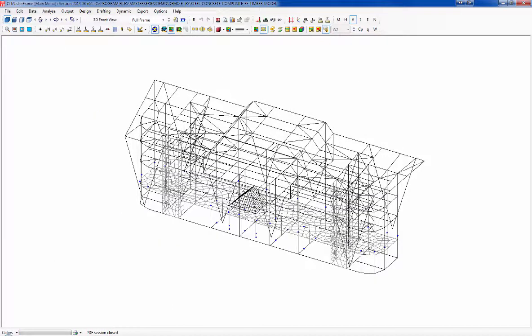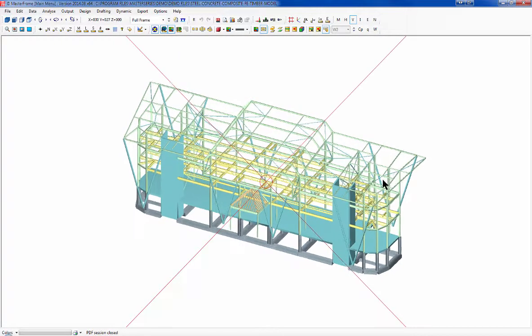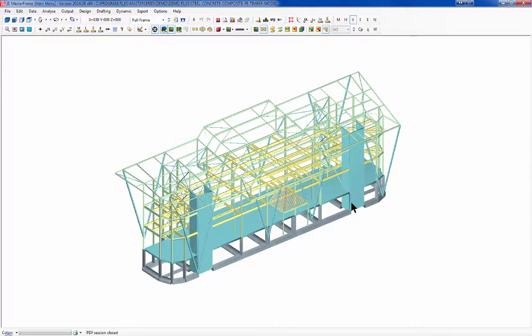So it's just loading in the frame, and the first thing we will notice is that this frame that I have looked at before and played with has got finer elements on it. It's got a transfer slab and it's got 2 shear cores. If I pull this up in 3D, we will see that we've got 2 shear cores. What we've actually got coming from the ground is a concrete sub with concrete columns, and then a concrete transfer slab, and then 2 shear cores,